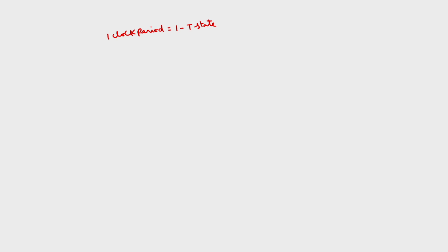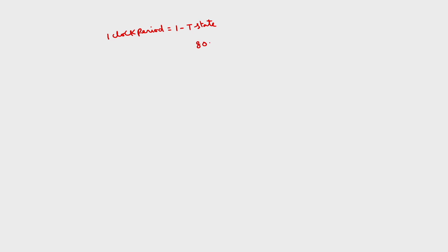If I take the microprocessor cycle, the 8086 bus cycle takes 4 T states. I will show what the T states are. If I want to read or write data, we require the address and data buses.